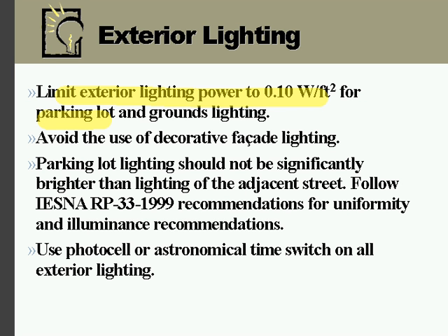And I was very involved in those numbers, and yes, you can do the lighting at these lower levels and still maintain good, adequate lighting, which is probably the most important thing to consider when you do go to lower light levels in exterior environments: don't just reduce the wattage, maybe add one more pole. Keep your lighting level as even as possible throughout the space.